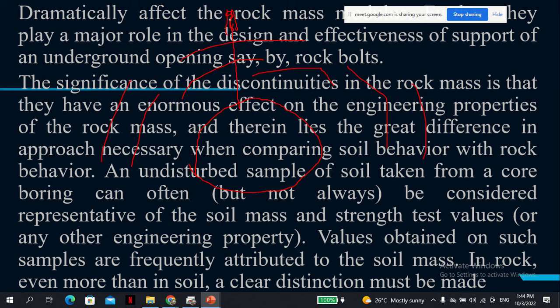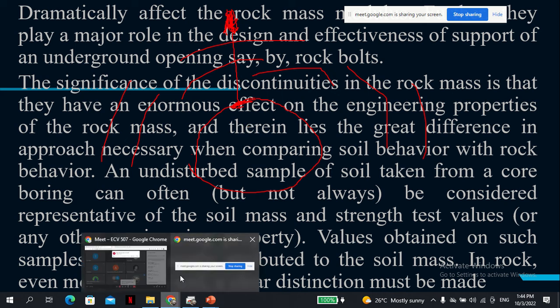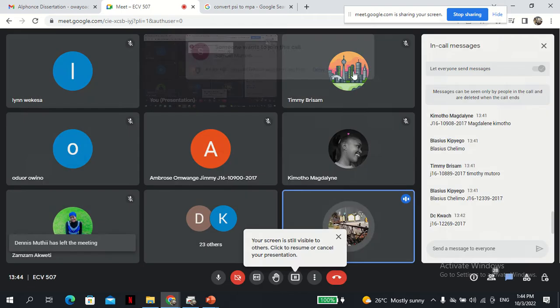Once you know that this is where the cracks are, you anchor it with grout there, and then you secure it firmly on the edge of the tunnel. So you can see the extent of the crack determines the design of the rock bolt. Of course, the amount of force you apply also matters, because you have to apply some force on the rock bolt